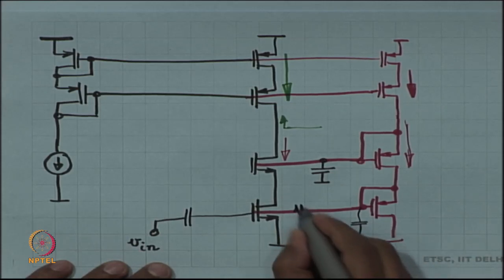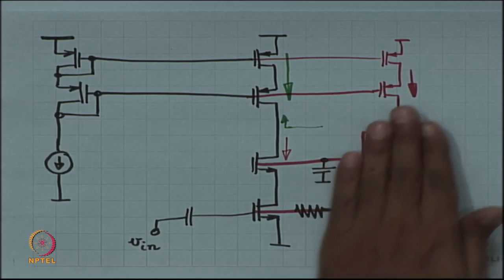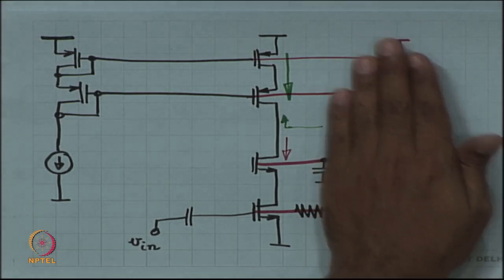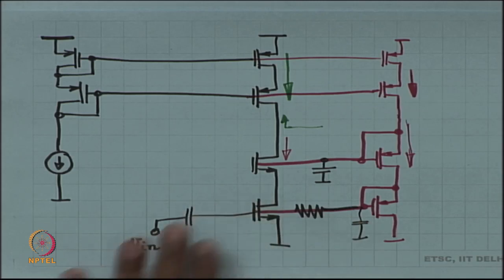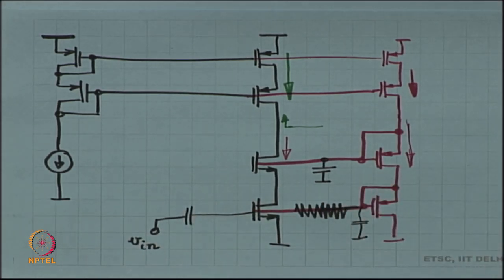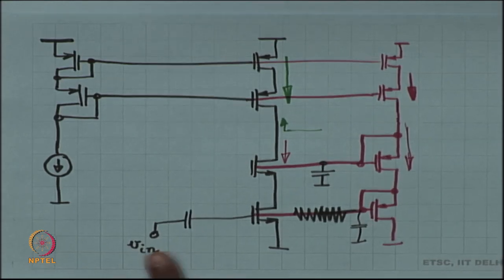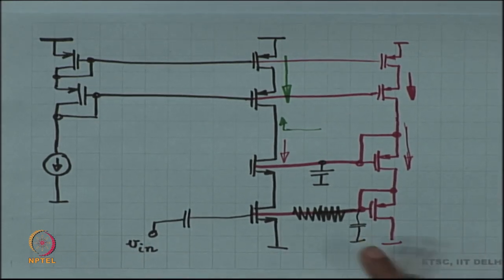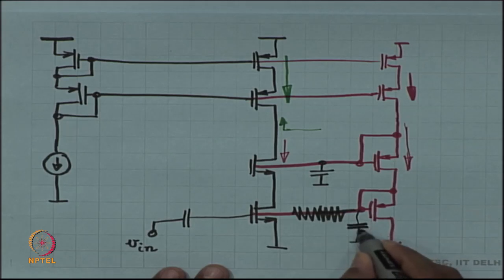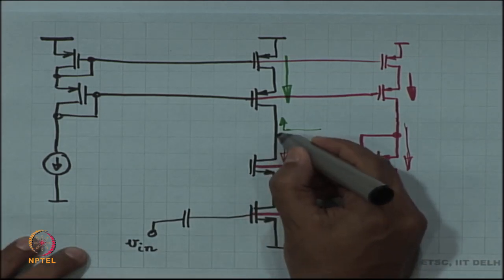And this has to be isolated out, okay, so that this current mirror side does not vibrate at all, right. You can place a very large resistance over here, such that this current mirror side does not change with the signal at all, okay, and at the same time you have to AC couple it to ground. Is this okay? And then the output is from here.